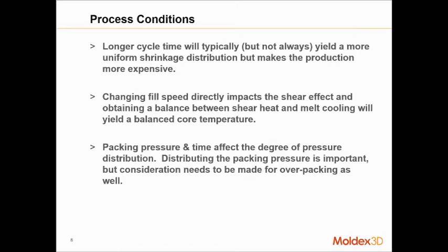When we're talking about filling and packing, we're impacting a lot of what's happening through the center of the part. So maybe like the 80%, I'll say, of the thickness is going to be impacted by what we call the core temperature. And that's going to be a lot of what we looked at with shear imbalance, and when we're looking at things like packing effect, we're talking more about what's happening on the core side.